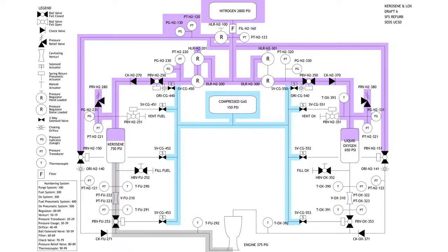So basically what happens is that we're just going to plug it up into that compressed gas tank, and it's going to split off in 8 different directions. And you'll notice that there's an orifice, CG540, CG440. What we're going to be doing is that when you open that pneumatic ball valve, 250 and 350, you don't want it to open instantaneously.